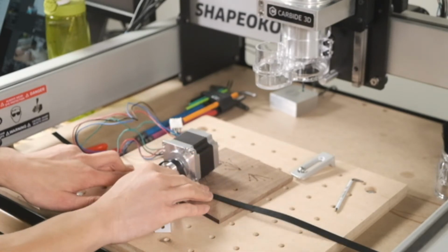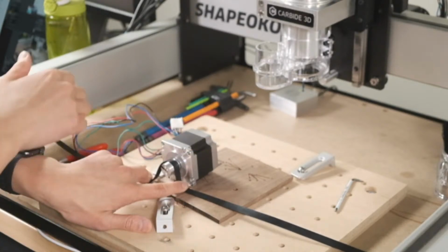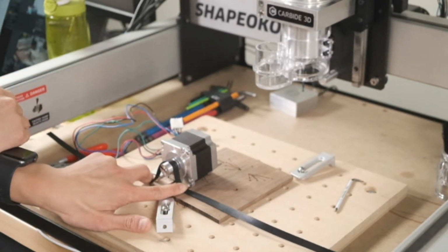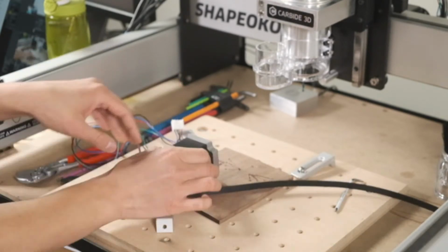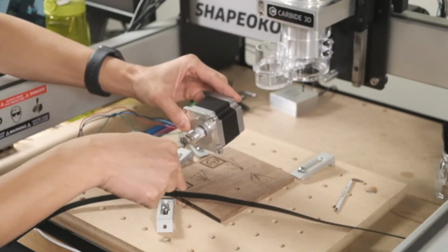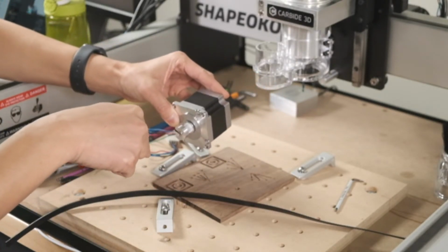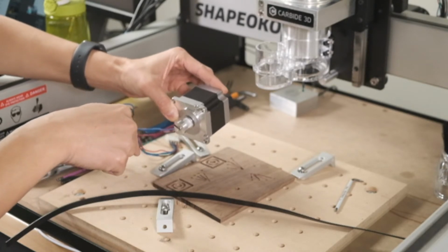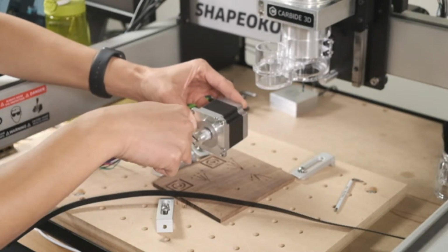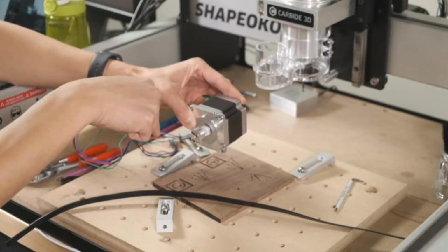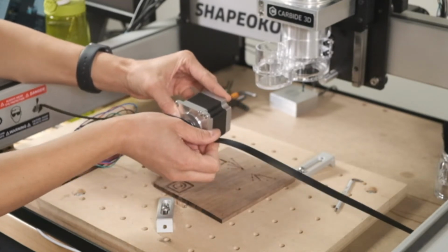So for that period of time, the machine is just not going to be moving, and that's usually what causes round holes to come out oval. Normally as you go around a hole, you travel in X, but if there's a little bit of backlash, the CNC thinks it's over here, and the stepper motor is always basically playing catch up. And once you reverse direction, it pulls up slack on the belt, and then it starts moving.